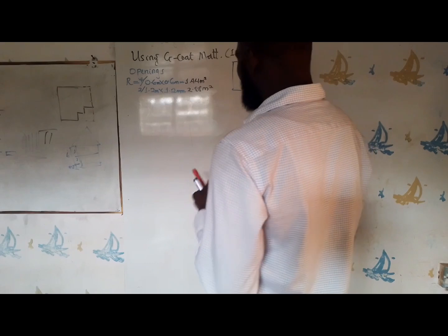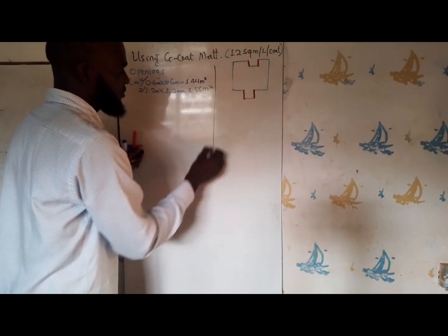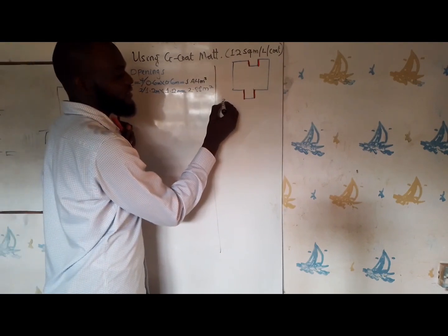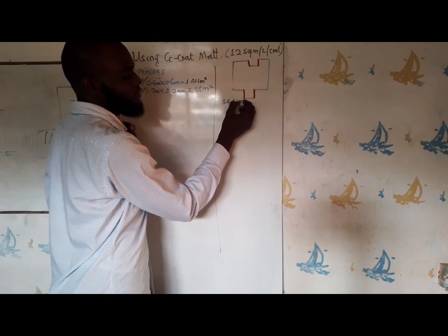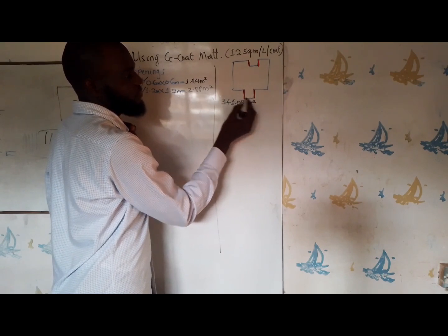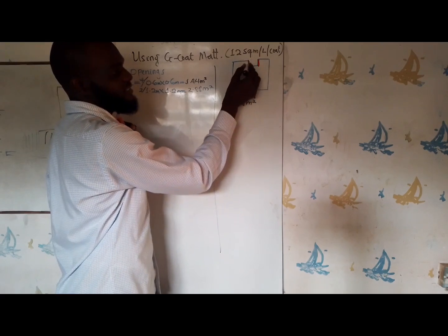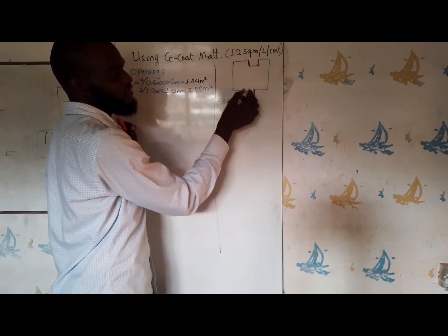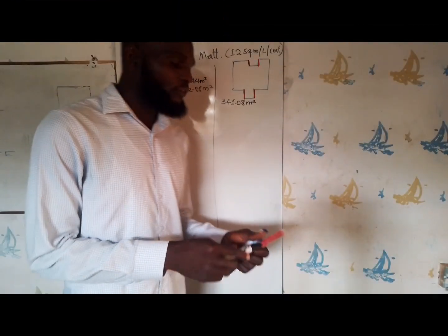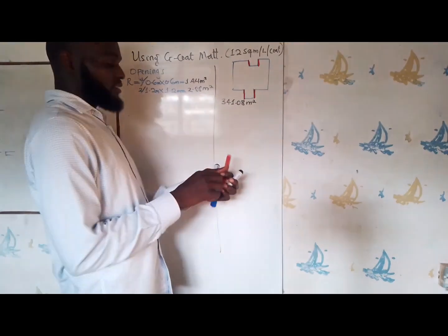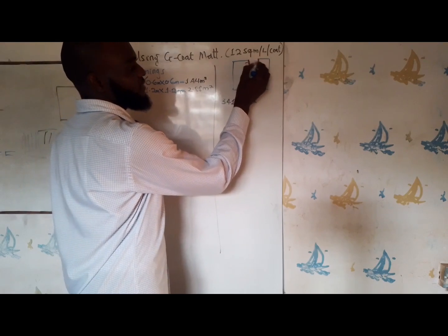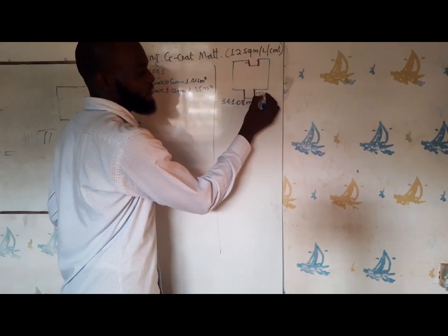Let's share this way. So let's do that now before we come back here. We got 341.008 or 07 square meters. So now we need to add this recess, these two sides, and this projection. What is the length of this space? Now we have the wall from our drawing. This is 900, this is 900. This one is 1.5.